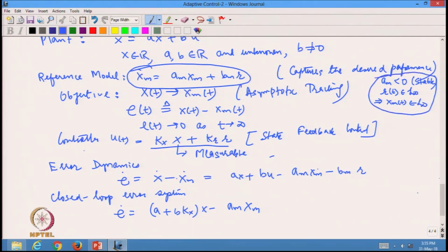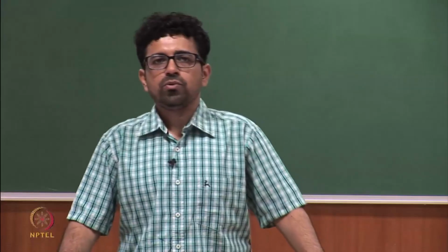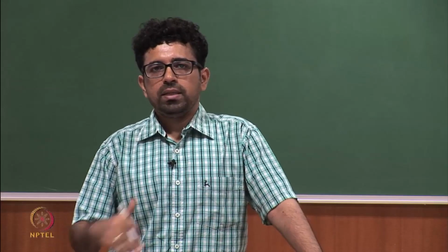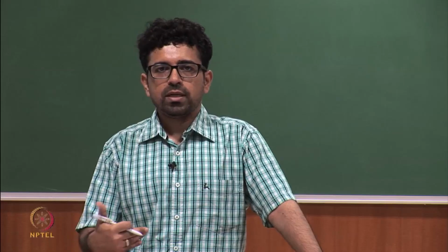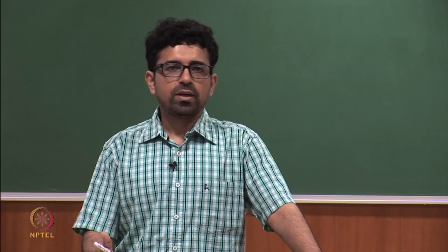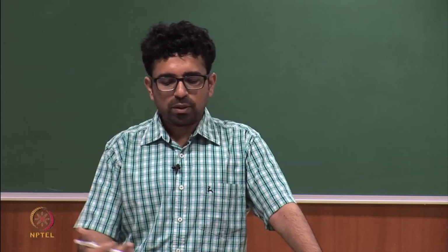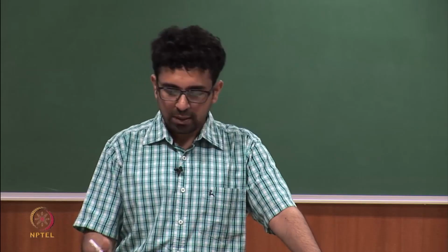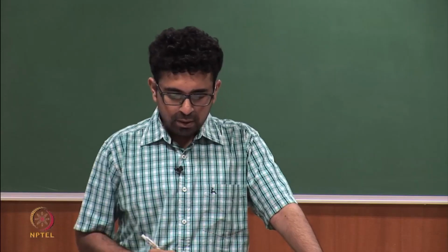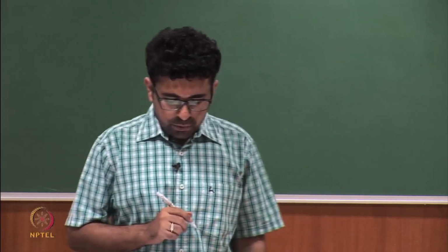So, you have to be very careful when choosing the reference model. It should be a stable system which should capture the desired transient performance, and the input to the reference model should be a bounded signal. Okay, so let us get back to our closed loop error system.